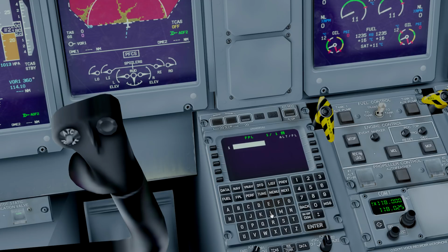Okay, so what we're going to do is enter our origin airport first of all. So that's Innsbruck, Lima Oscar Whiskey India, the ICAO code, and then you just hit enter. All right, and as you enter it, you can see that you get some information about this particular airport, and you just click accept. Now the way you continue is a bit strange. Again, there's no scratch pad, it's really getting used to. What you have to do right now is simply enter the next waypoint first.